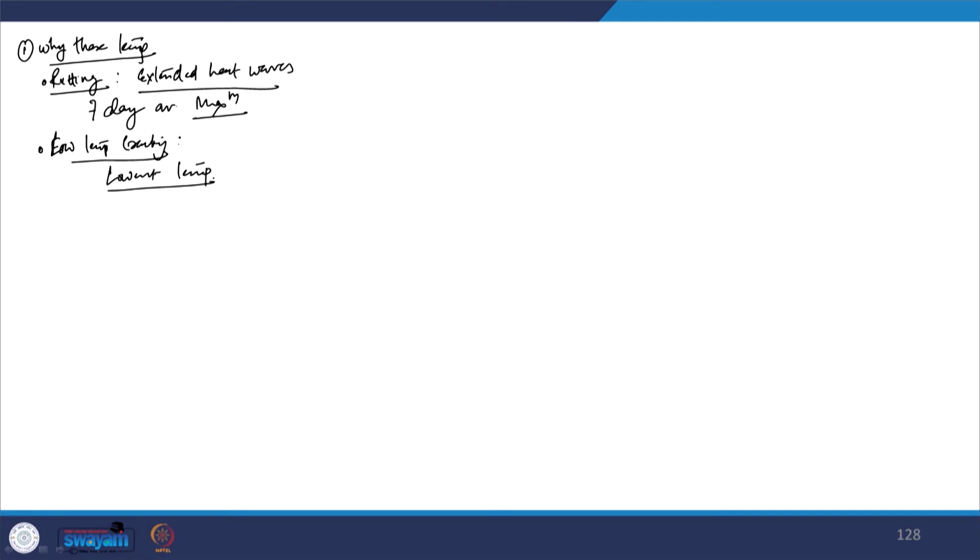Okay. So, why is the lowest temperature chosen? Because let us understand how low temperature cracking will occur. When the temperature reduces, the top layer, the HMA, will try to contract, and therefore a tensile stress will be developed between the HMA layer and the base course. If this stress exceeds the tensile strength of the HMA layer, the HMA layer will crack, alright.